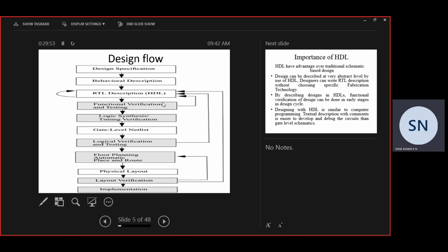Always the source needs to be connected to the power supply. For the positive power supply, the source is connected to VDD. The same way for NMOS, the source is ground. So I will write source here and drain here for N2 and gate.